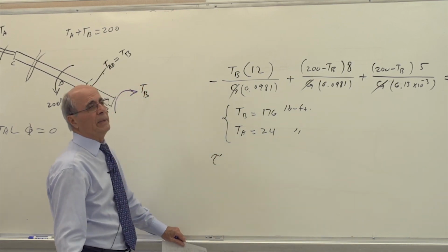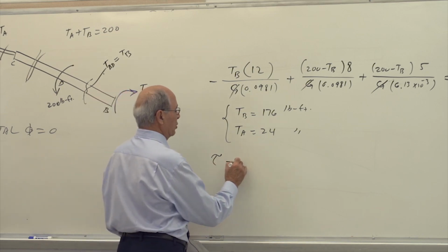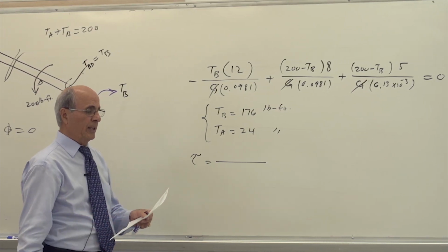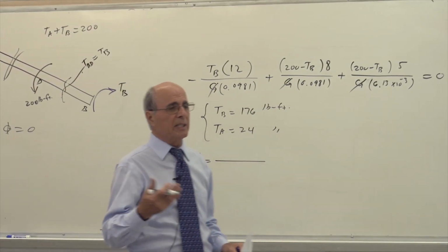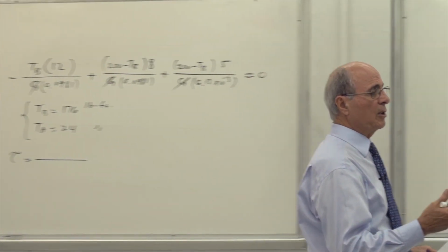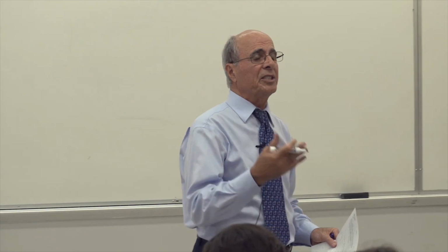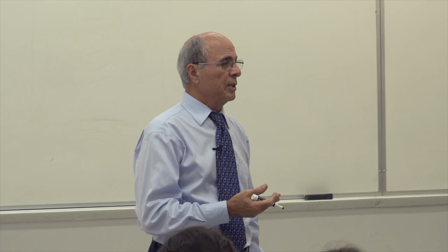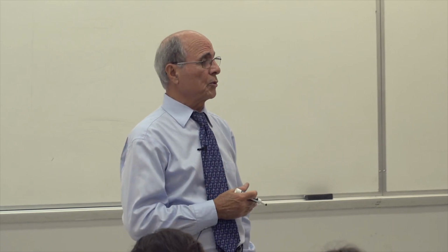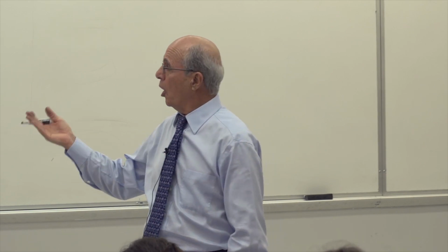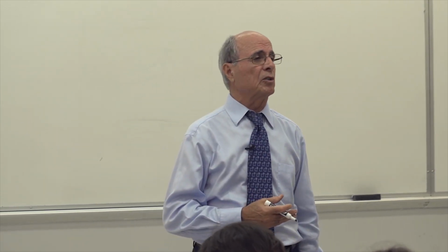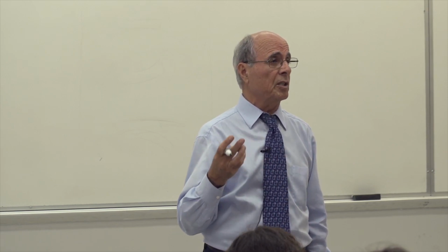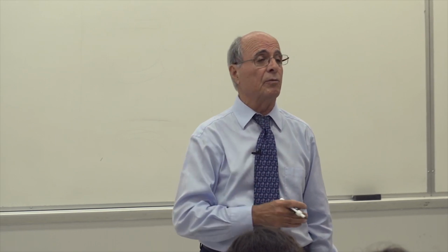The rest is not that difficult. However, many mistakes. Tau equal to. Now here is the mistake that I saw. I don't know how many times I have to explain that. I said, what is the unit of stress, guys? Let's review that, because there are at least 1/3 of people who do not understand this unit of stress yet. They are making mistakes. What's the unit of stress? PSI, or did you ever see me using pound per foot square? Why are you changing the I or J to the foot square? And I don't understand, or to foot to the power. By the way, if you find anywhere in the strength of materials book the unit of stress as pound per foot square, which at least 10 of you calculated that way.